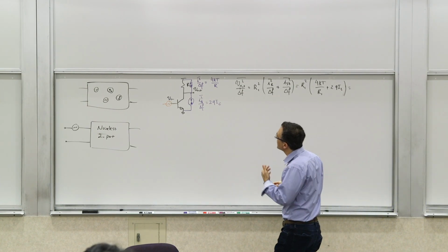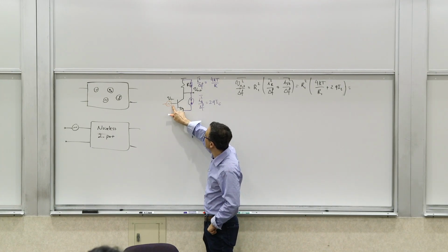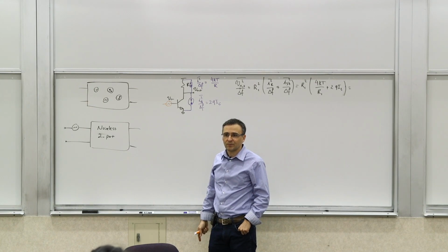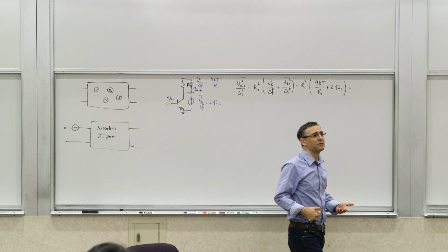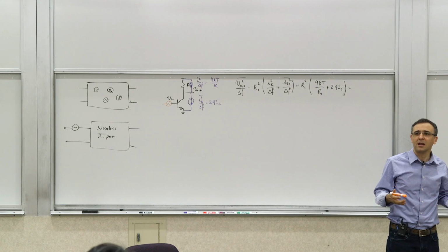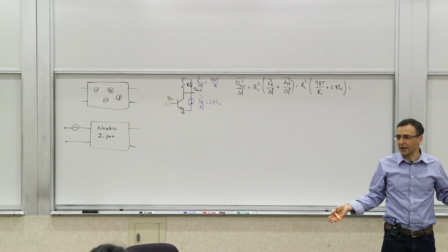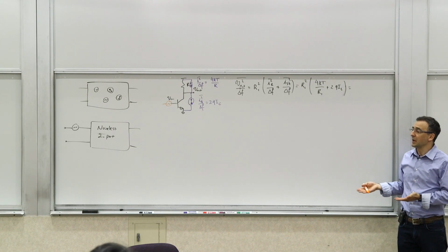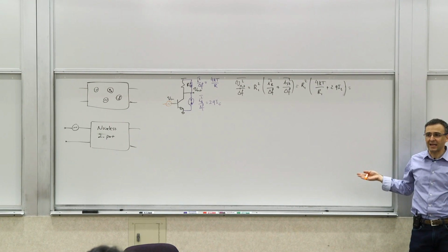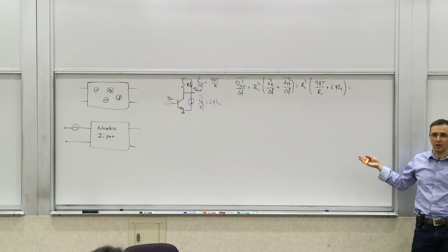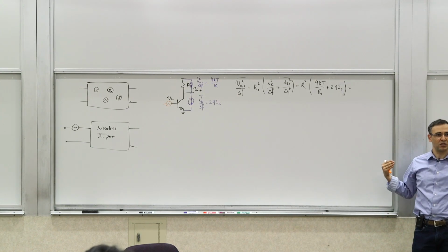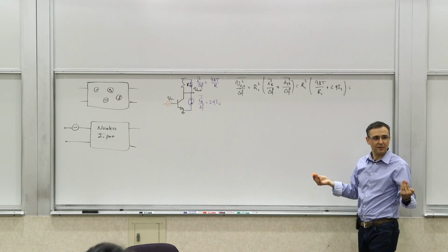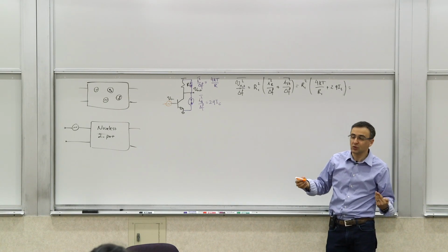And the way to do it is simple, because you know the transfer function from this point to that point, right? And we know how noise behaves with respect to a transfer function. We've looked at LTI systems. We know it's the transfer function magnitude squared. Right now, we are not dealing with frequency effects so far. So what's the transfer function? It's the DC gain. It's gm R1. So you need to divide by gm R1 squared, both of them squared, to get the effective input noise that would produce this kind of output.